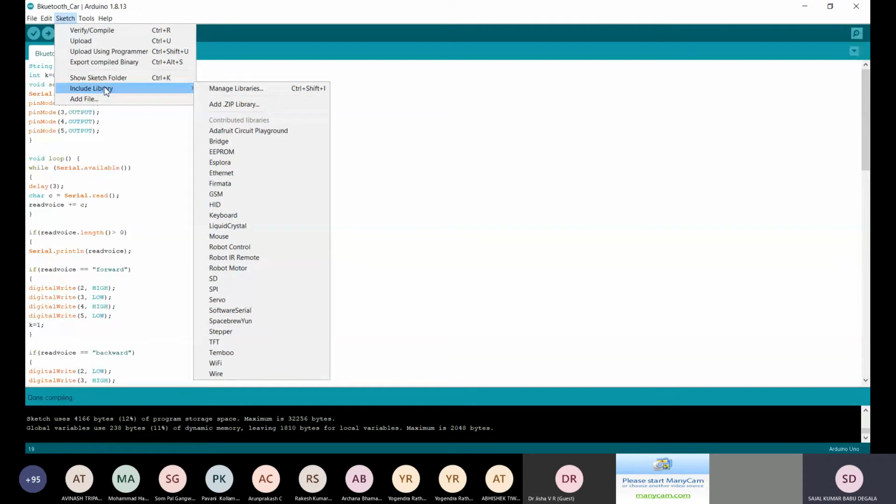If you are using the ultrasonic sensor, what it is going to do is first emit the ultrasonic waves. The waves will strike an object, and then the wave will come back as an echo. The sensor is going to receive the echo and you are going to calculate the time.